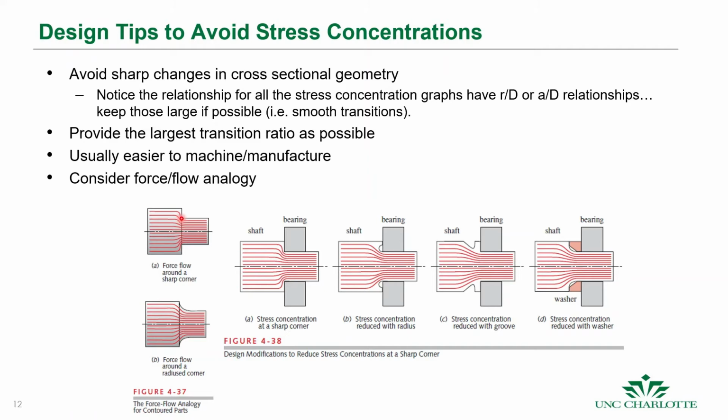All right, now instead, if you have the option, what you would like to do is make these gradients less steep, or make these lines less packed in. And so you can almost imagine it, so this force flow concept is like, if you imagine these force lines flowing through, okay, if you go from here and now these lines have to flow through here, and you have the same number of lines, the only way for these lines, which are spread out, to go through this area, which is smaller, is for you to push all those lines together.